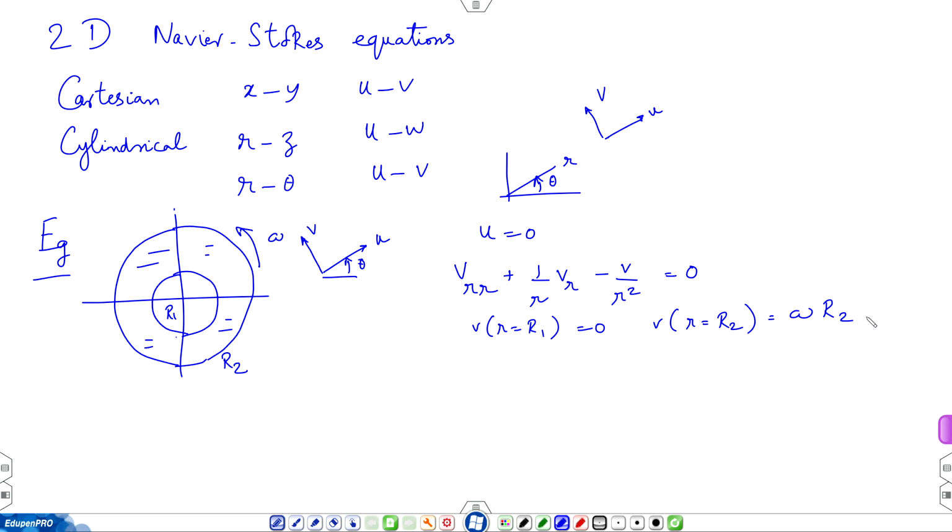So, the fully developed flow approximation linearizes the Navier-Stokes equation. So, one way of simplifying Navier-Stokes is to look for ways and means to linearize it. You can reduce its dimensionality, 3D to 2D to 1D. You can try eliminating the time derivative by saying I am looking at only the steady part of it. And then next is you try to linearize it. These are options available to simplify.